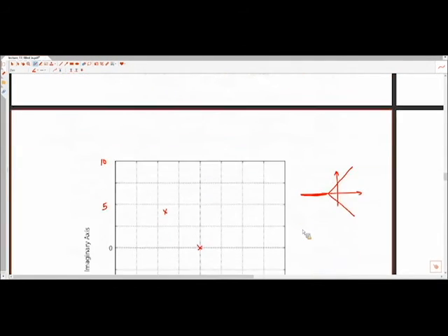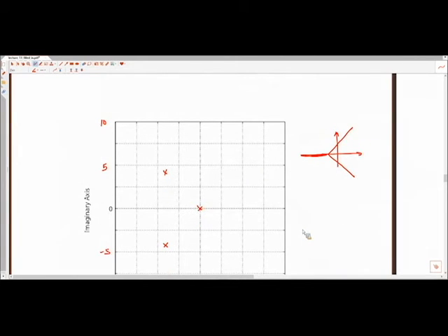Okay, so now we have an asymptote. So -8/3, right, is what is that, 2 2/3, right? So 2 2/3, this is 2.5. Let me use a different color for a construction line here. This is -2.5, so we're just a little bit to the left of -2.5. So this is going to be our asymptote. This is sigma A. And then I have my asymptotes going off at -180.